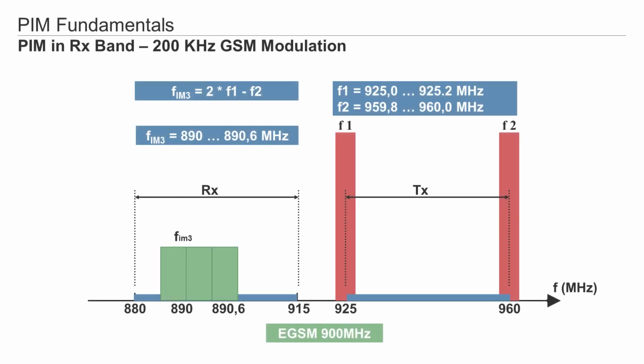A carrier always uses several frequencies. It is the frequency band that enables carriers to offer different mobile services to their customers. Because of that, PIM can block main parts of the RX band, where the BTS is listening to the mobile devices. The result is that the base station can no longer operate at 100%.